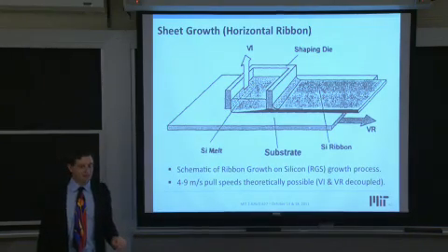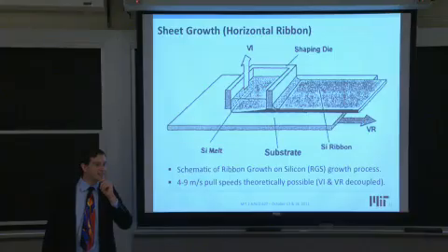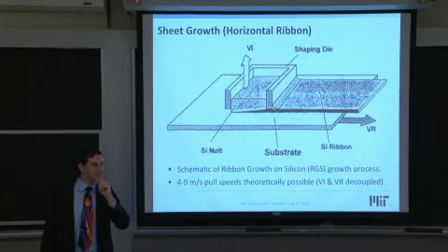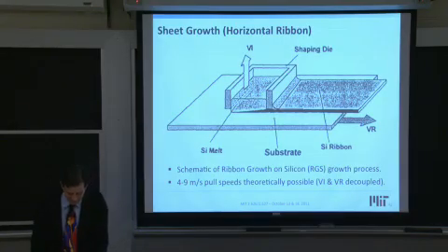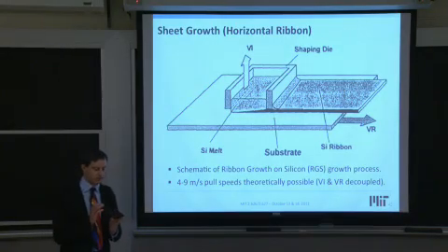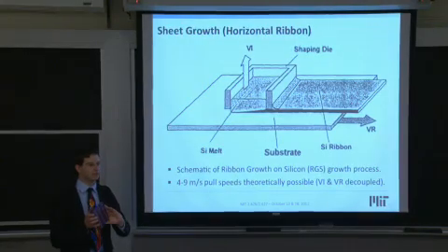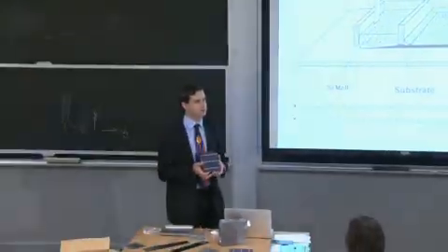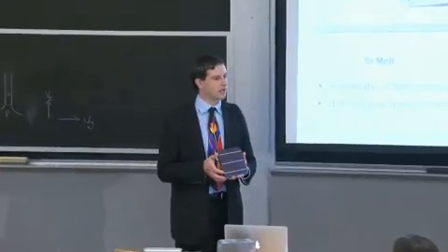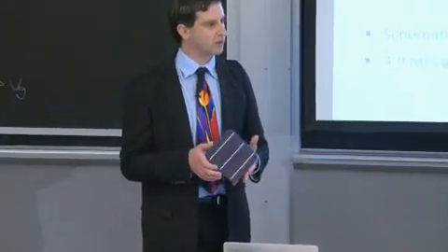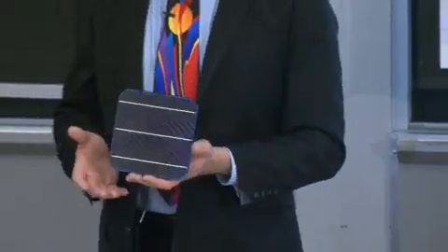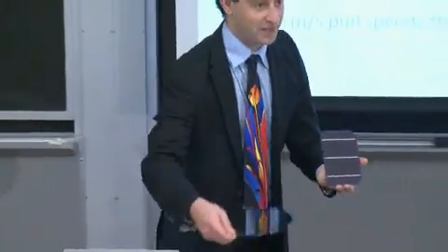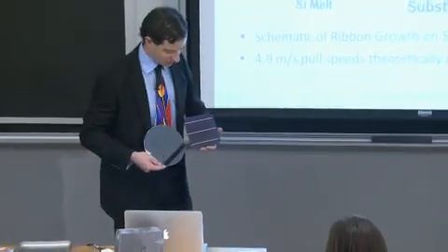Question? You had mentioned form factor for these wafers before. Is there a standard form factor for solar cell manufacturing? Yep. So the standard form factor today is akin to this one right here. It's about a 15.6 by 15.6 centimeter squared lateral dimension form factor for the wafer. And I can pass this one around as well. This right here is what's called a pseudo-square. You can see the edges are kind of rounded off. And that's because it came from a CZ wafer like this one. It was just chopped out of it.